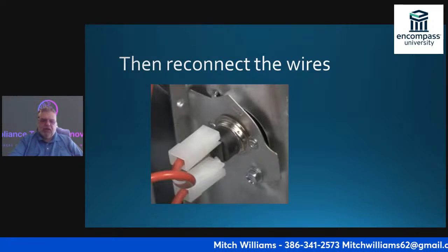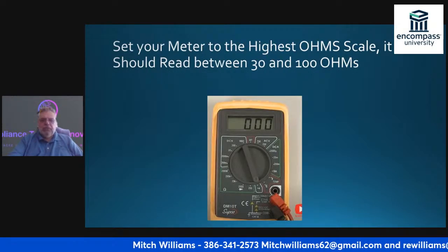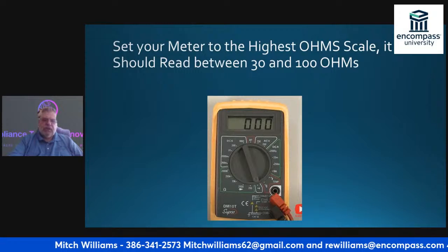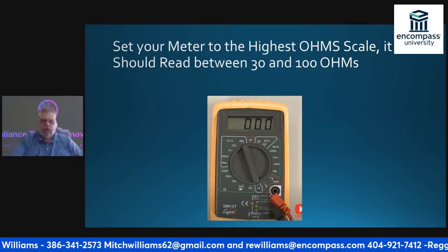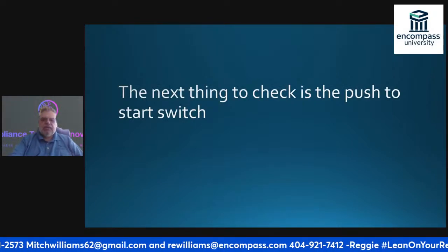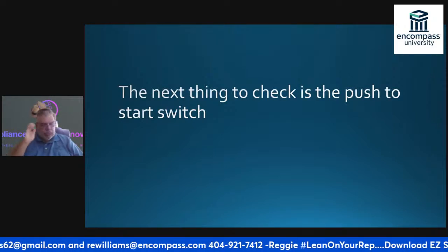I'm going to reconnect all the wires. I'm going to set my meter to the highest ohms scale. It should read between 30 and 100 ohms. The next thing is to push the push to start switch.